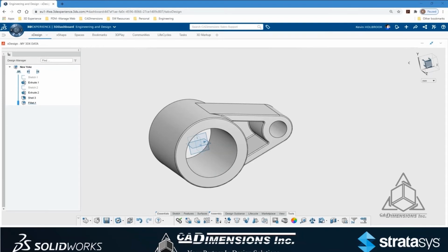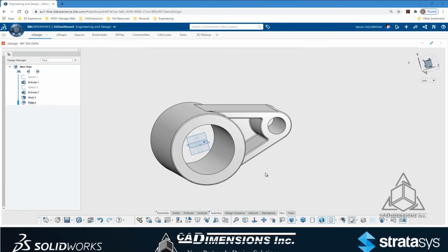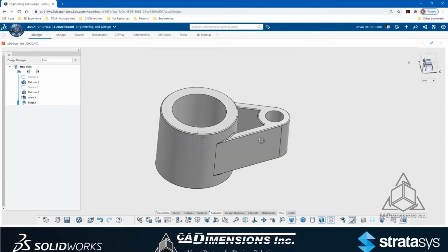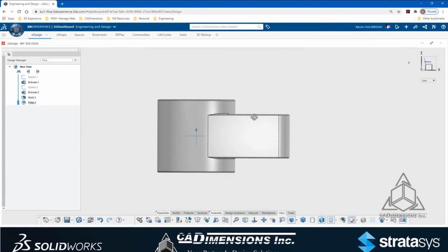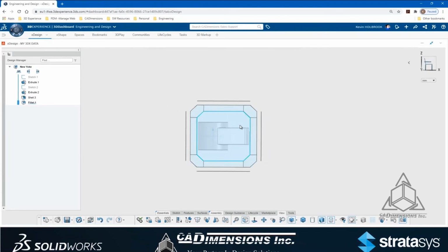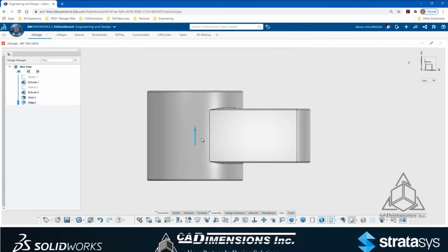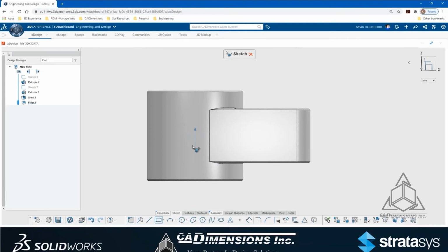Okay. So let's continue on. I need to have the same ear on the left side, but before I do that, I need to create a little cutout on the inside. And I'm going to do this with a revolve. And we'll sketch something on a plane, essentially a rectangle, because that's where I'm going to start.